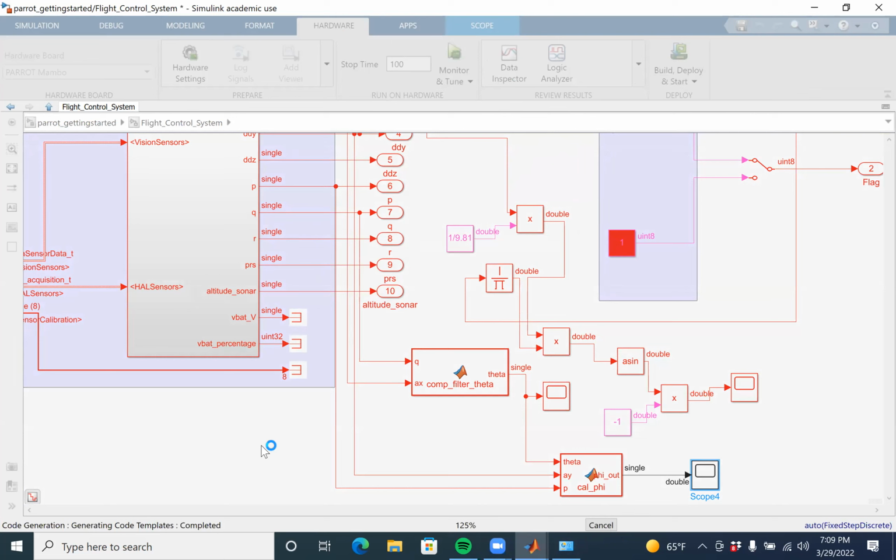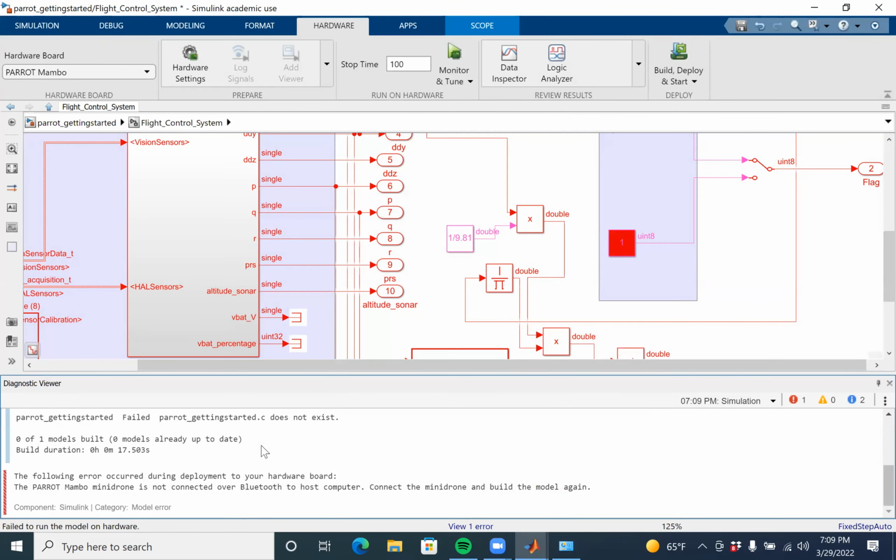So why did I use this block? Because what I want to show you in the next few minutes is this. If you think about it, when the quadcopter is in level flight, what is the set point? Set point is 0. Do you agree with me? Which means error is nothing but the angle of phi and theta, whatever angle I'm getting. Do you agree with me? So what I can do is, in this function itself, I can choose a suitable constant and connect this directly to the motor mixing block, which is on the top, and that will control the speed of the motors.